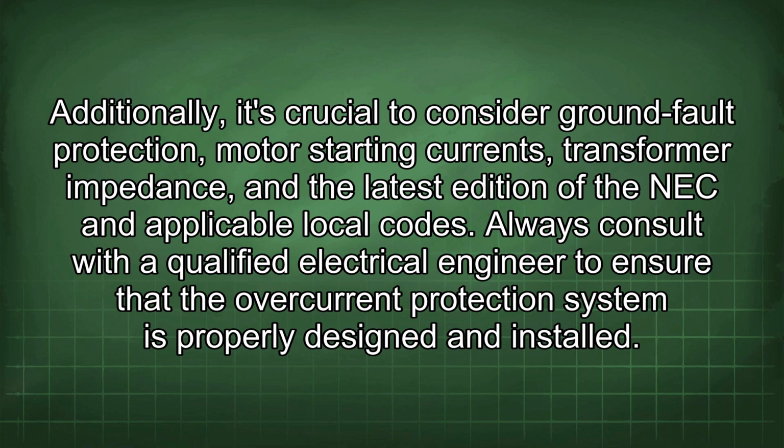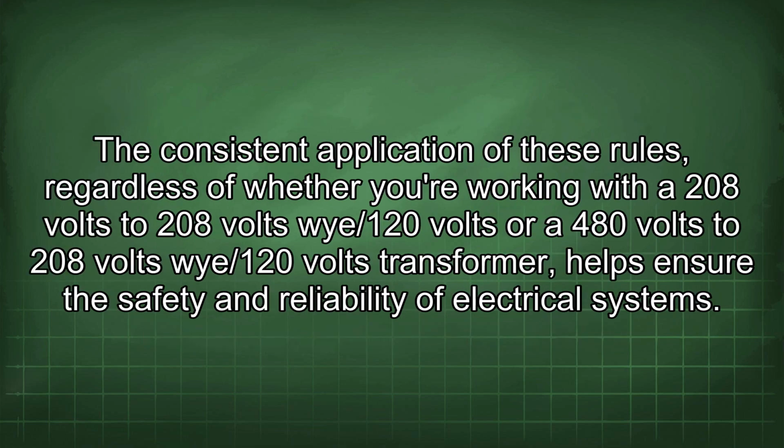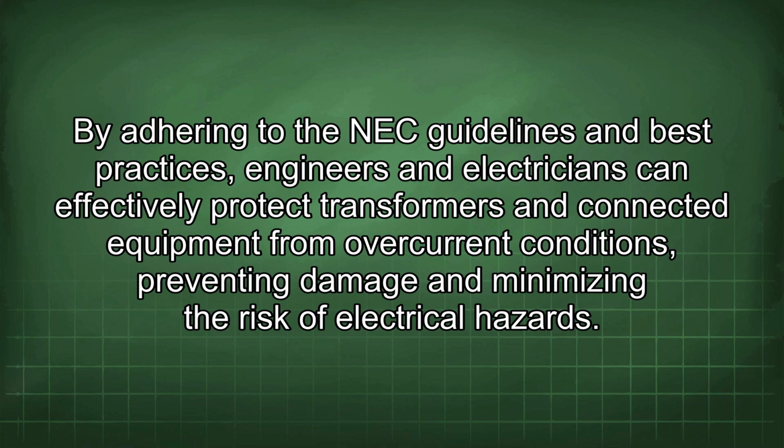designed and installed. The consistent application of these rules, regardless of whether you're working with a 208 volts to 208 volts Y/120 volts or 480 volts to 208 volts Y/120 volts transformer, helps ensure the safety and reliability of electrical systems. By adhering to the NEC guidelines and best practices, engineers and electricians can effectively protect transformers and connected equipment from overcurrent conditions, preventing damage and minimizing the risk of electrical hazards.